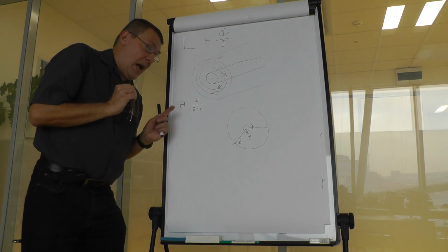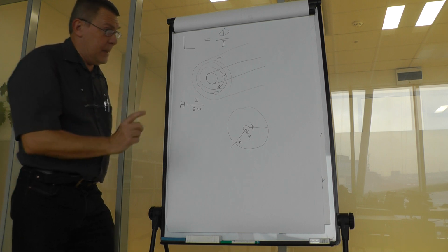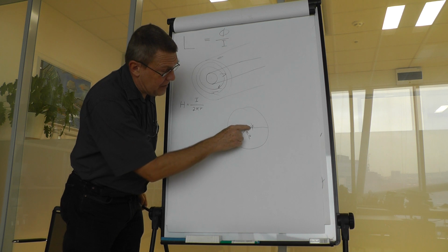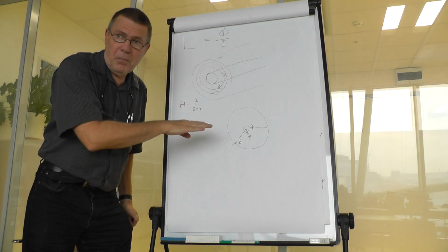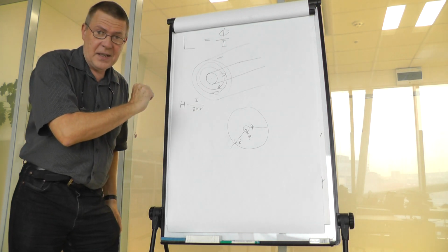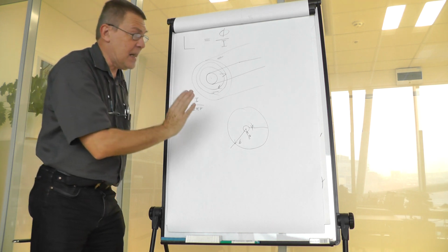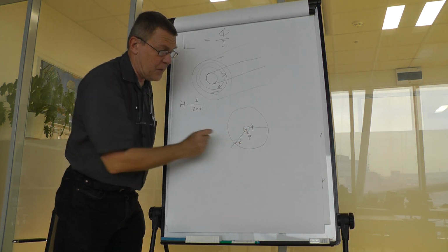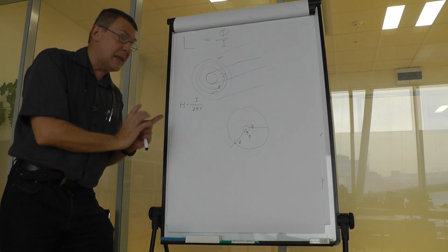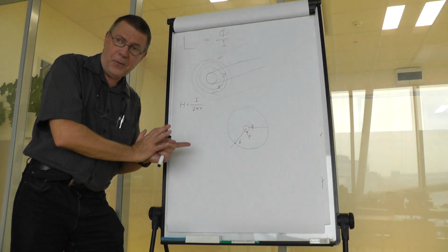Now, if we want to make an academic point, there is some flux running through the inner conductor. We will neglect it now because most applications of the coaxial cable use high frequencies, and we will learn later that the current only flows on the surface of the conductor. We will return to that case later to find out the remaining portion of the magnetic field.